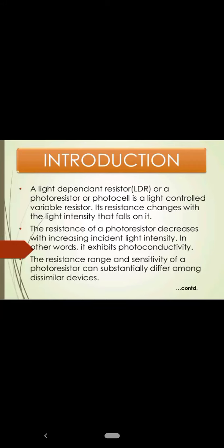Kiran Yadav. In this session I will discuss the light dependent resistor. So let's start with the introduction of LDR. The short name of light dependent resistor is LDR, or it is also known as photoresistor or photocell. It is a light controlled variable resistor. Its resistance changes with the light intensity that falls on it.